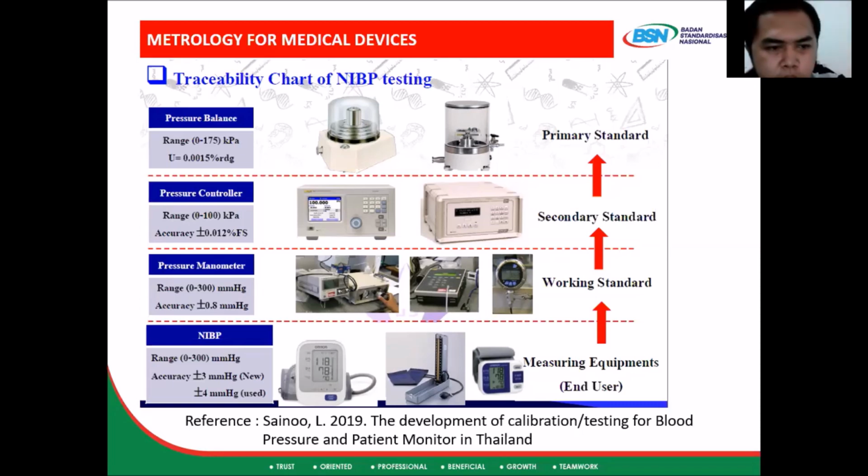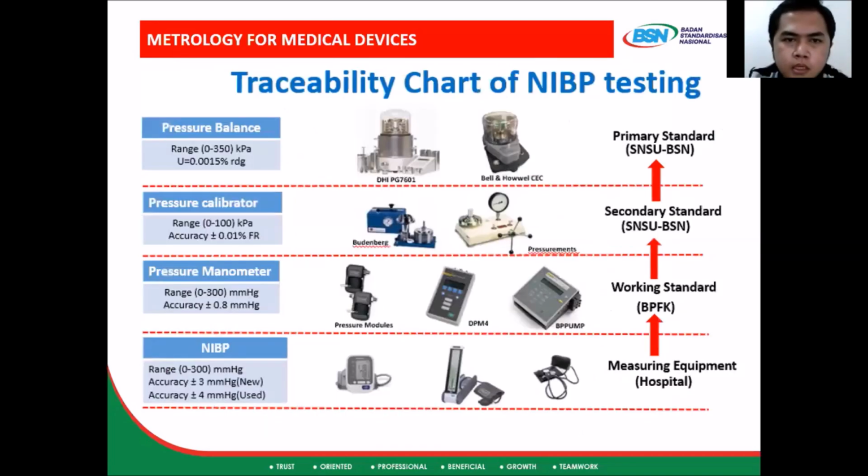And this pressure manometer is calibrated using the pressure controller. This is their secondary standard in NIMT Thailand. Then it is calibrated to the primary standard, which is the pressure balance, with a smaller uncertainty. And this is in our nation,